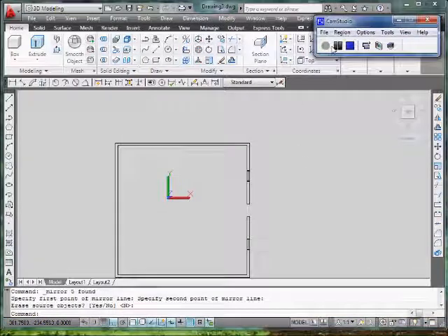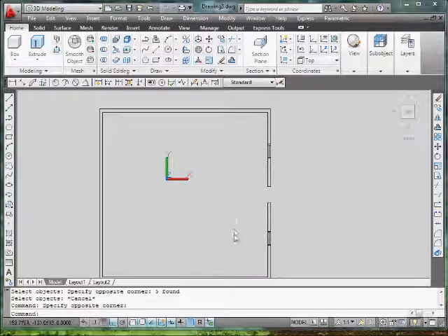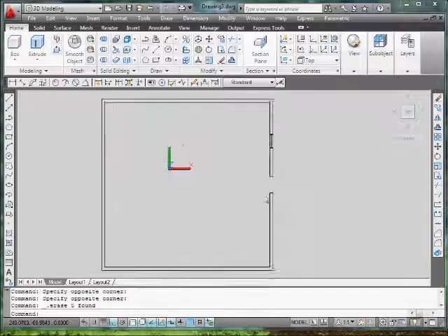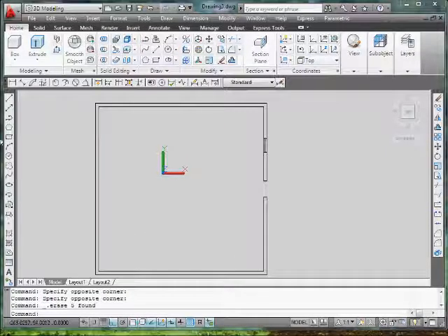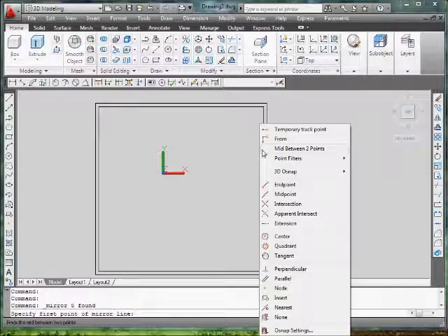The thing about the other option, if you guys don't feel like, or you don't have a wall to use as a midpoint, let's say I'm trying to make a mirror of this between this point here and this point here, what you can do is select the window, go to mirror, and you do shift and right click, and it gives you that options menu here where the snappings are.